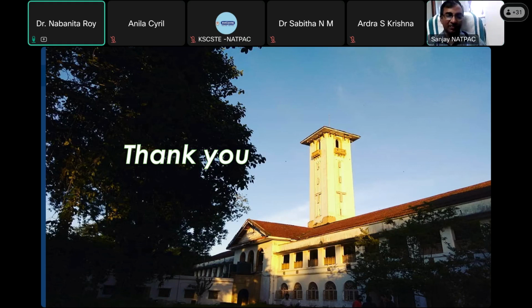Yes. So basically, in my study, we have only considered just after construction, just after opening to traffic. We collected the data within 3 to 6 months. In my opinion, if we can take more time series data, every 6 months, skid resistance data by some technique, maybe some image technique, or if you have a skid resistance trailer, then it will be better to know how it is deteriorating.